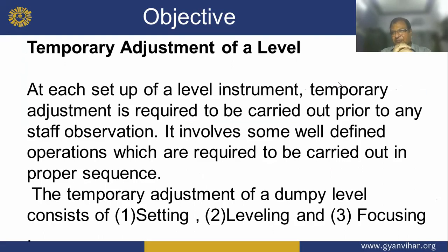So what you will need is temporary adjustment of a level at the site. It is a must for you. This is a temporary adjustment of the level. You should know the permanent one also. At each set of the level, instrument temporary adjustment is required to be carried out prior to any observation.